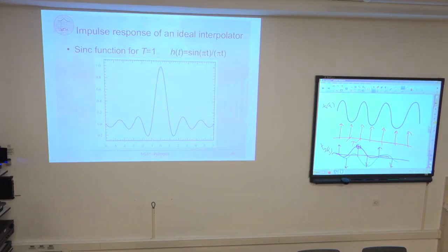So the actual implementation is always truncated to a given length on the left side. And that is paid for by the addition of delay. You introduce delay into the actual reconstruction, whatever number of samples, for example 10 samples, and create the output signal with this design delay, I would say. So the only way that I can take the contribution of these 10 further samples is to acquire them and to compute the output only after this delay of 10 samples.